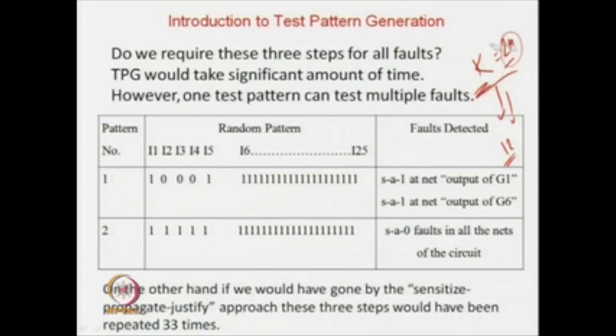So, now again we are going another level down, so that even if we have some say p number of faults after all the fault collapsing, we require at least p number of test patterns to detect them. Because 2n is the number of faults, if n is the number of nets in the circuit, at max we have 2n stuck-at faults, stuck-at 0 and stuck-at 1 for each line. By collapsing we have reduced it to p.